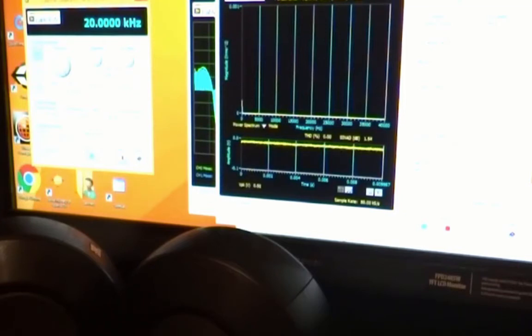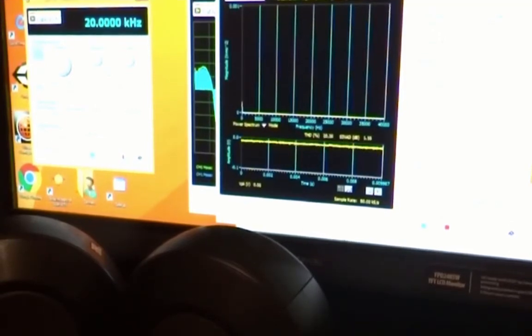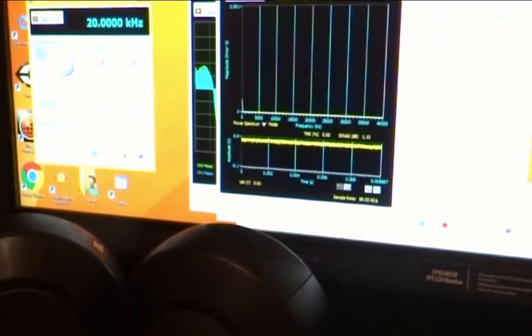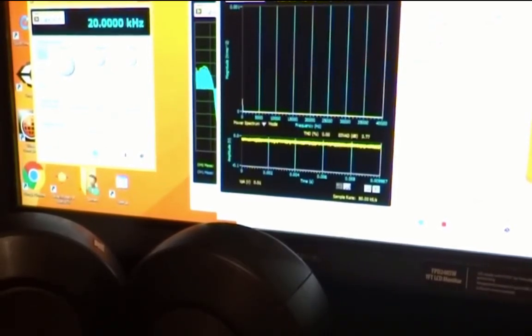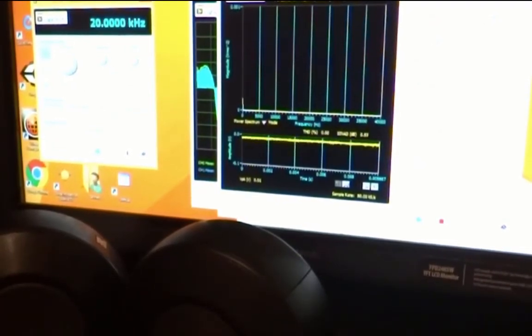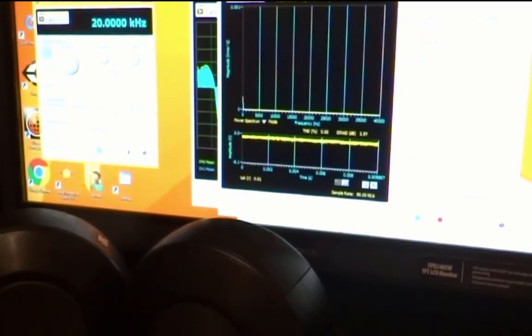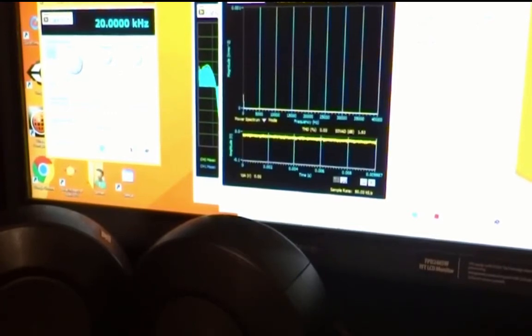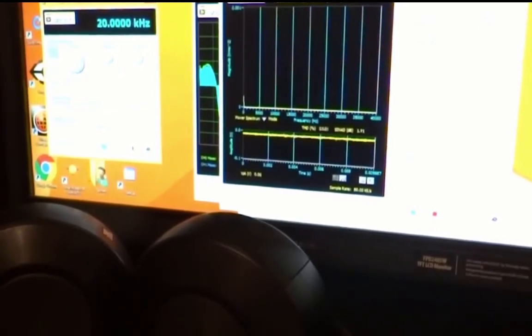So, there's an illustration of double sideband amplitude modulation. An actual AM radio station and receiver setup uses a variation of this technique. One reason we're able to do this double sideband trick here is that we had the same carrier for both the modulator and the demodulator. For this technique to work, it's extraordinarily important that the frequencies and the phase match. In particular, the phase. If the phase between your modulator and your demodulator isn't locked, then you get situations where you don't get as much volume out.